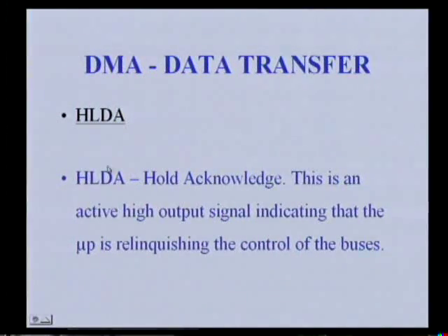Next pin, hold acknowledge pin. Hold acknowledge is an active high output signal indicating that the microprocessor is relinquishing the control of the buses. That is, all the buses will be in tri-state, that is in high impedance state, so that these buses can be used by the DMA controller.